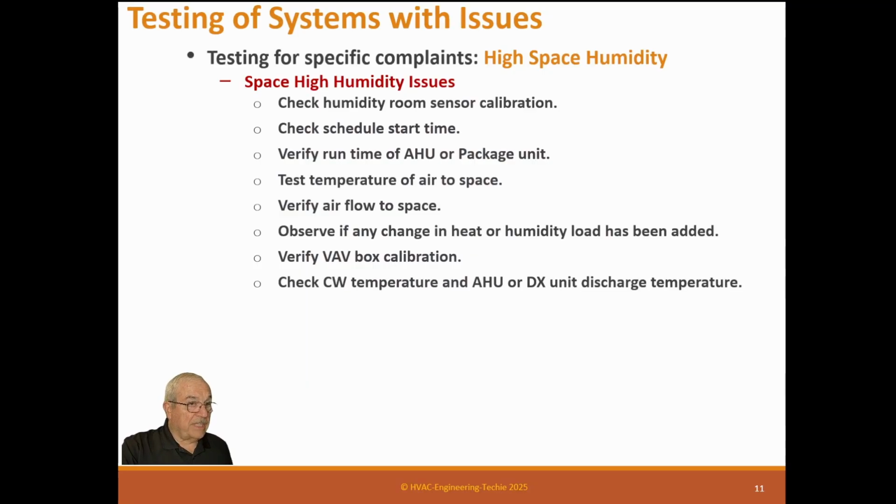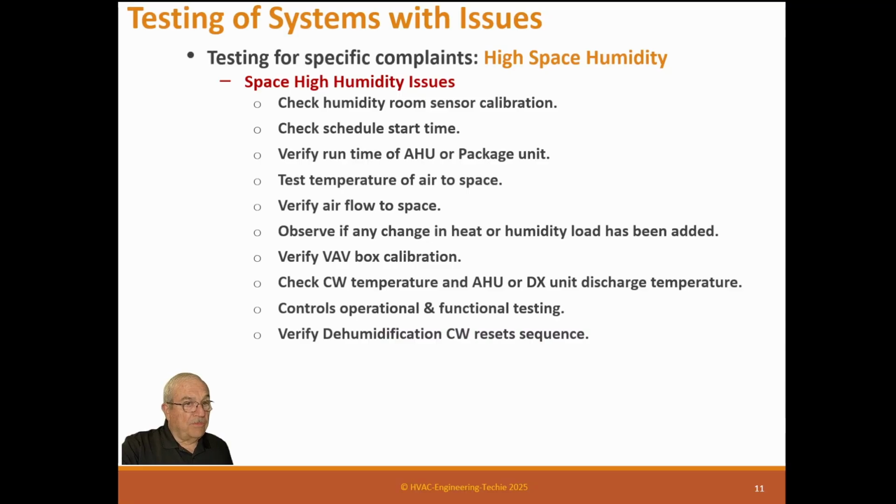Verify VAV box calibration. Again, check the chill water temperature in air at the air handling unit or the DX unit discharge temperature. Controls operational and functional testing. Verify dehumidification, chill water reset sequences. If you have a dehumidification sequence, and if you don't, maybe you should add one.